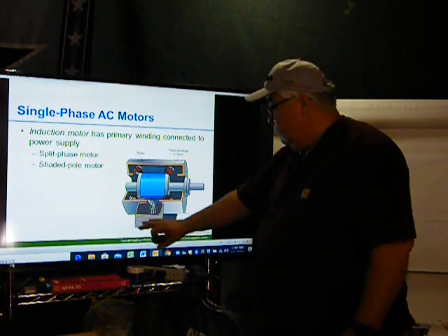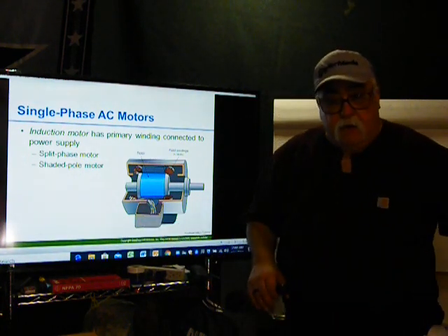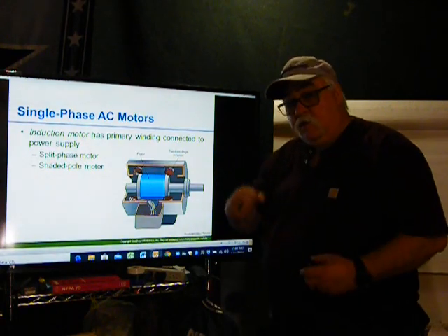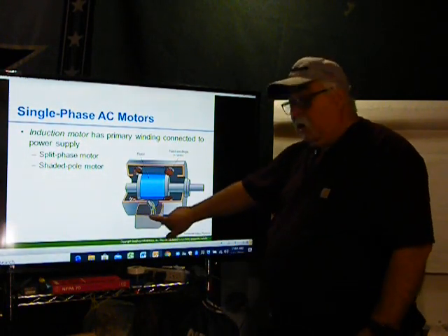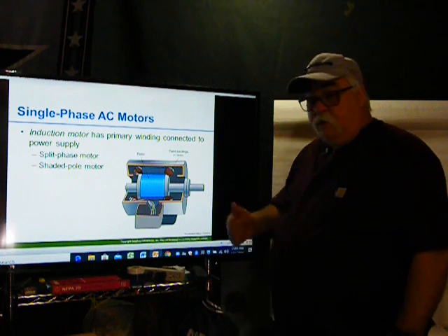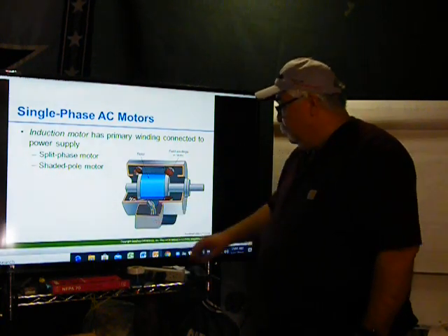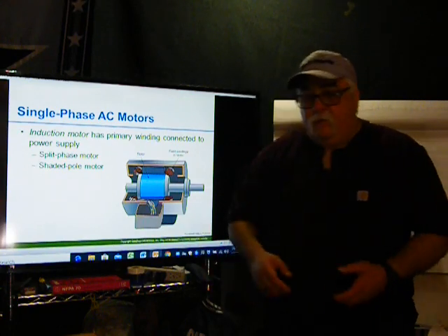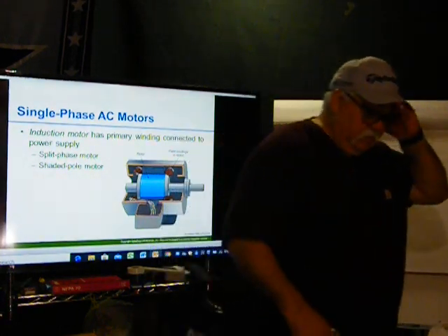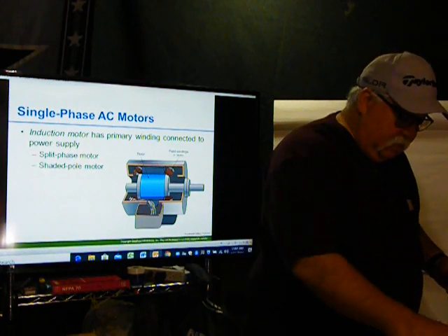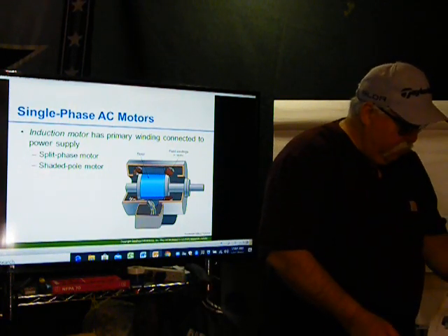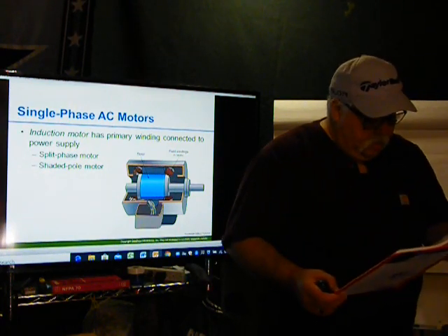If you ever hear anybody talk about a knuckle where you make your connections, they call it a knuckle because you usually bust your knuckles trying to get these wires back inside, especially on those 100 horsepower motors. So this is where your connections would be. That would be called the knuckle. The slang for it is knuckle instead of connection box or J box or whatever you want to call it.